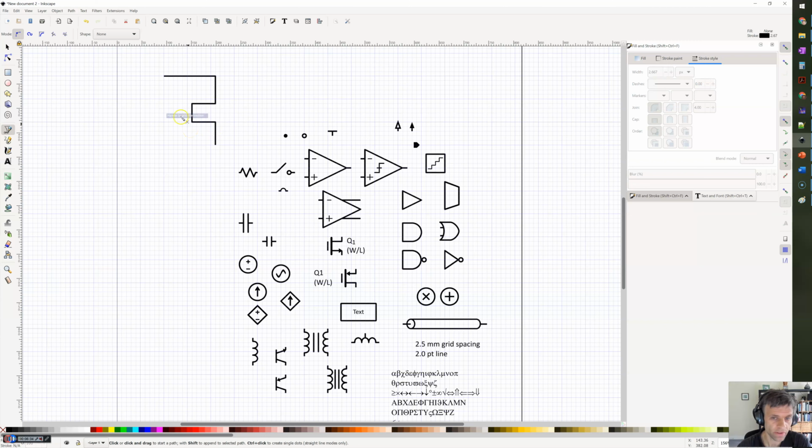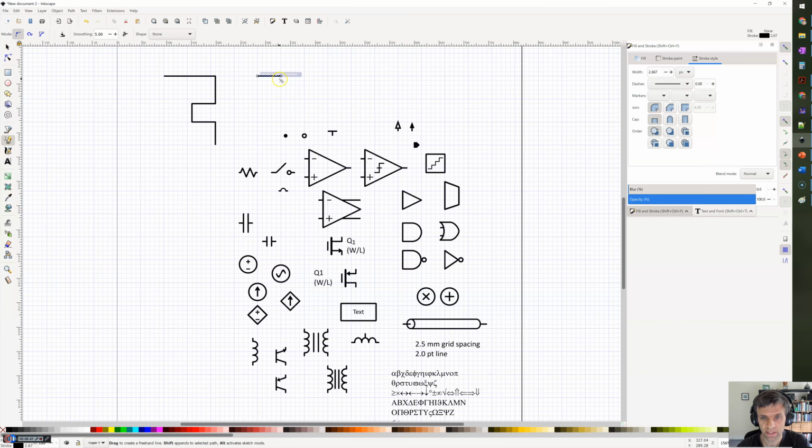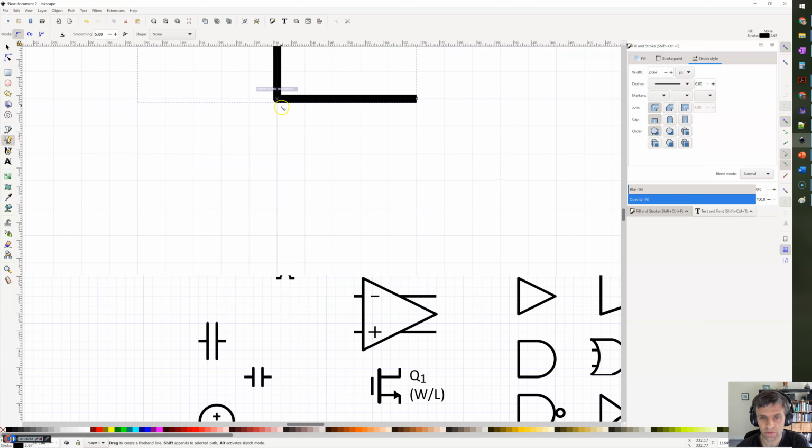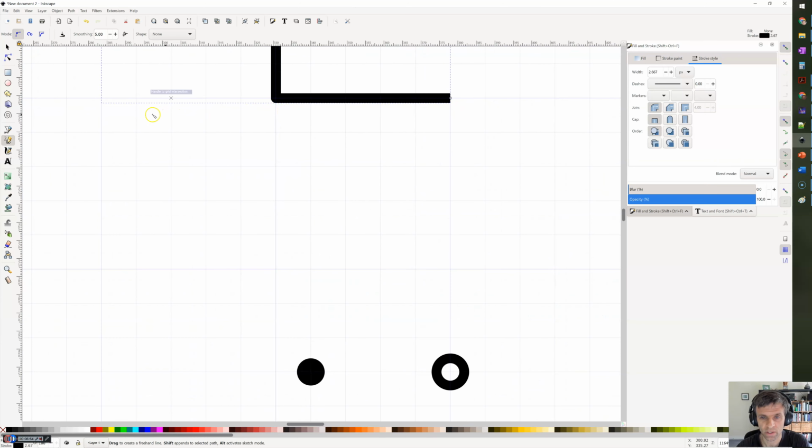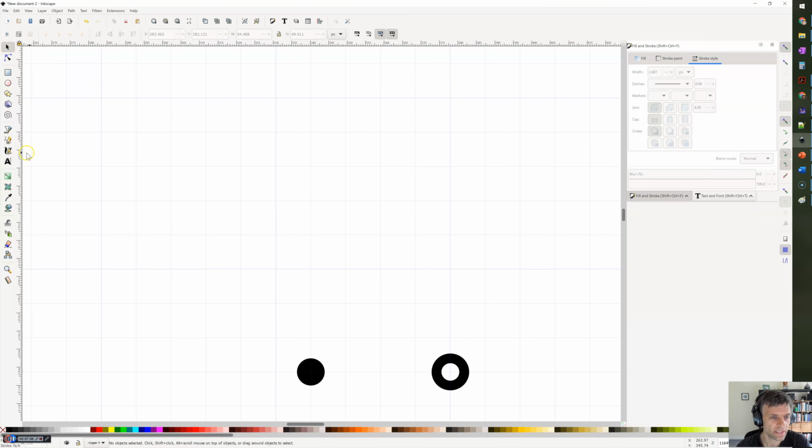Okay, so another thing to watch out for: it may be tempting to use the pencil tool and draw your lines one segment at a time. And it may look like this is working okay for you, right? And it can seem simple, but in fact, if you zoom in close enough, you can have problems at the corners, depending on how you define the line caps. So actually, it combined these pencil tools into one path, but let me show another example here where this can get messed up.